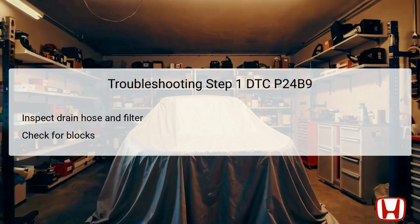The first step in troubleshooting DTC P24B9 involves checking the EVAP leak check module and the EVAP canister filter for any blockage. This requires removing these components to inspect hoses and filters visually. A blockage in the hoses can inhibit the proper flow of vapors, leading to erroneous pressure readings, which may trigger the code.